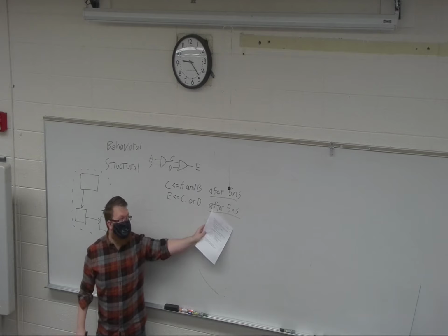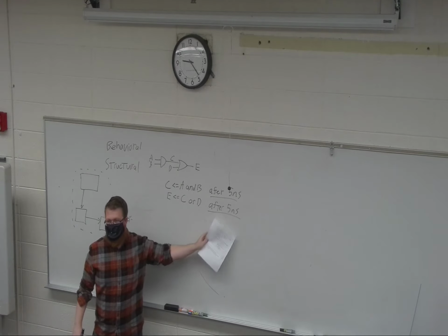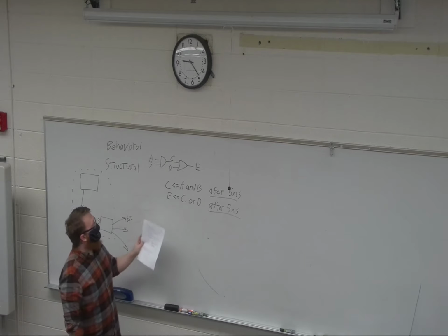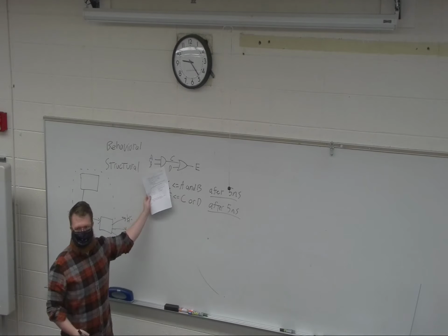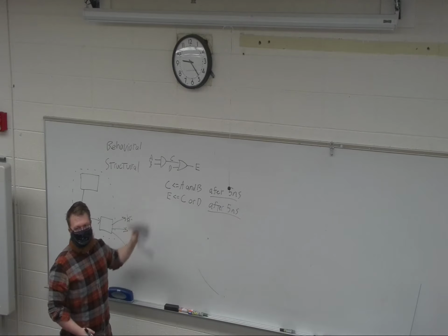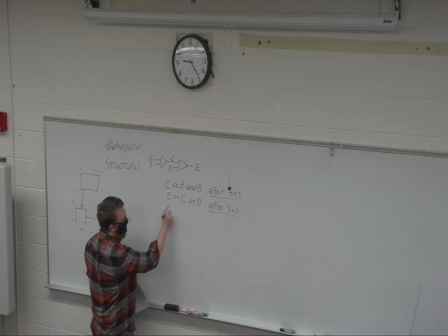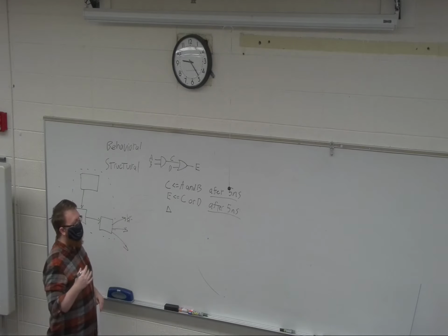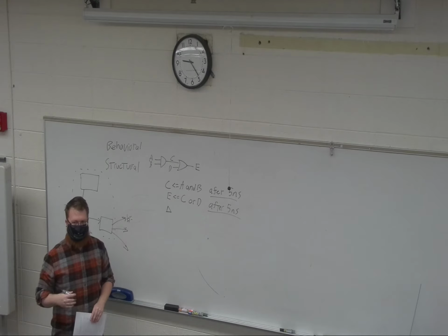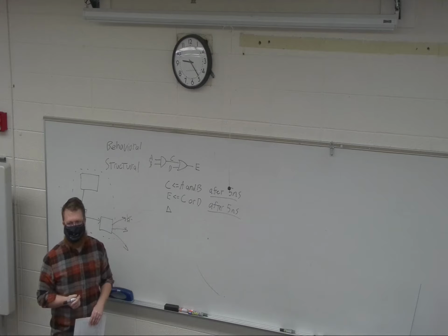So we know. Close. It's actually so the simulator knows. Because otherwise it doesn't. Pre-synthesis simulation doesn't know that there's a propagation delay, right? And so they'll introduce this term, delta, where it will happen after a short amount of time, which is as short as the simulator will make it, essentially.